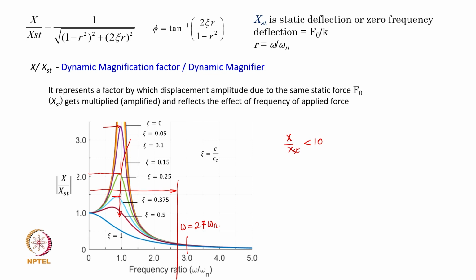Particularly just to highlight that point, of course, in a different context we will learn it a little better, but once you cross this resonance, let us say from this point onwards, just have a look at the advantage that you are going to gain by increasing the damping, hardly any, right. So, as long as you are working away from resonance, you really do not gain anything.